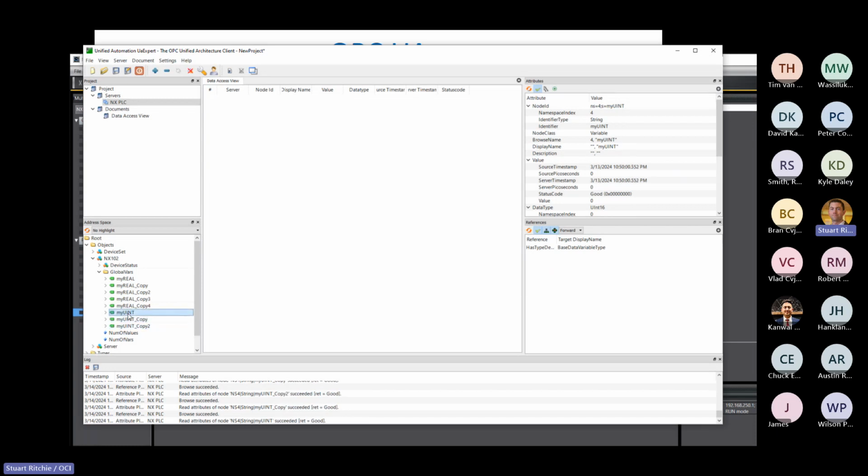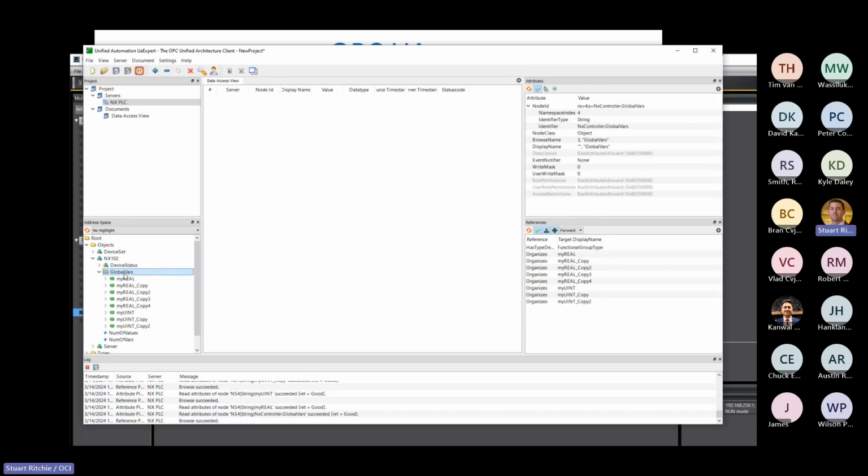Okay. Now this is just a browsing tool. If this were SCADA software, I could select this from the SCADA software and tie it to a level gauge, for example, on my screen, and really save that middle step. There are lots of other advantages to OPC-UA. It's another one we could probably do a whole class on, but a simple implementation is very easy to set up, and it's a big time saver when you're developing a SCADA system primarily. So any questions on OPC-UA?